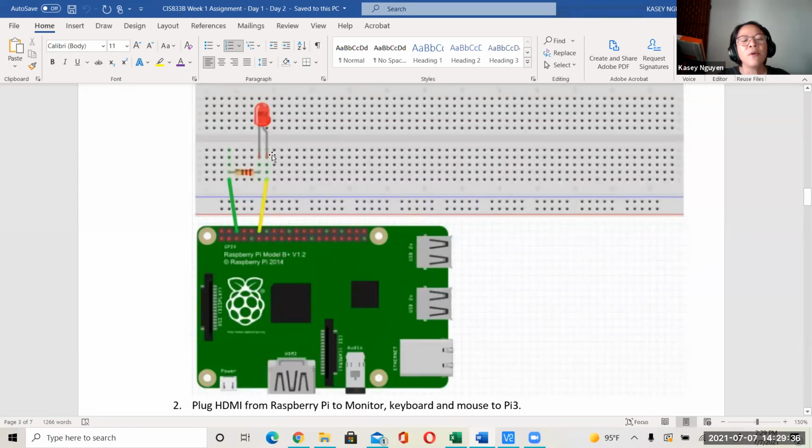And for electronics components that we are using in this class, when you are connecting to the breadboard, as long as you are having the direct line connecting to the wire, it should be able to transmit the signal down that path. So you want to connect your jumper wire, the male end, the one with the pin here, and then you would then connect the female to the GPIO.